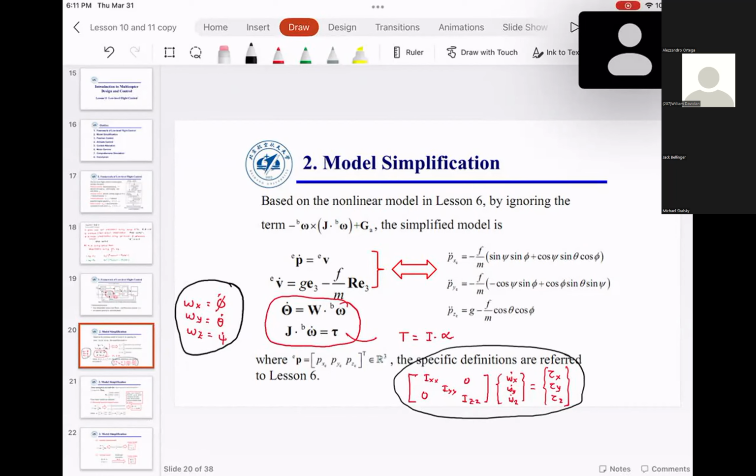Now, please try to understand there is something important that happens. We have an under-actuated system, which means the Mambo in the stable hover cannot go left or right. So it needs to roll or pitch and then travel in that direction.